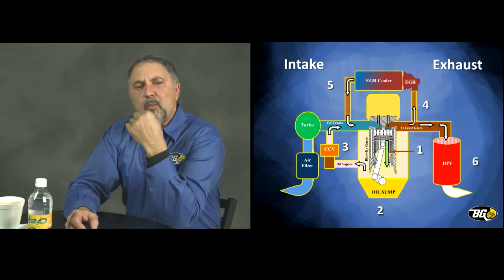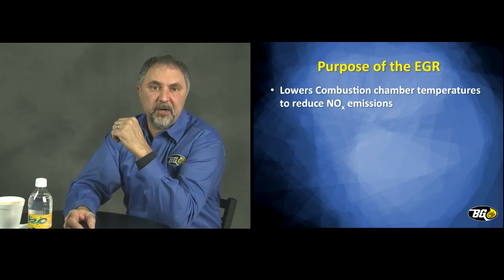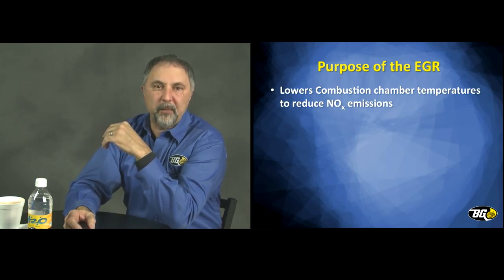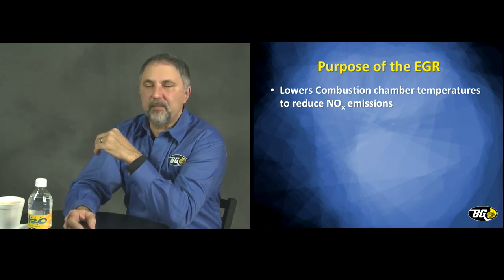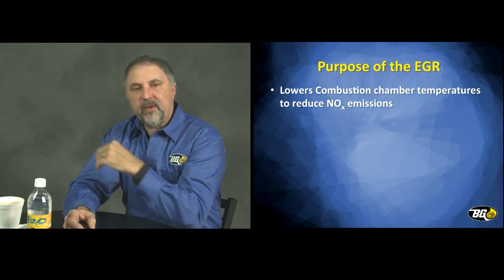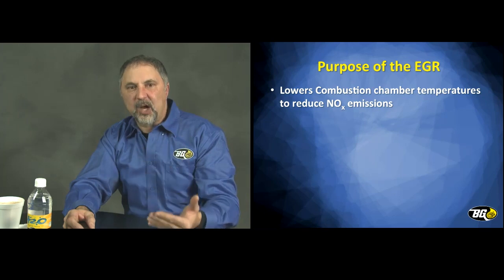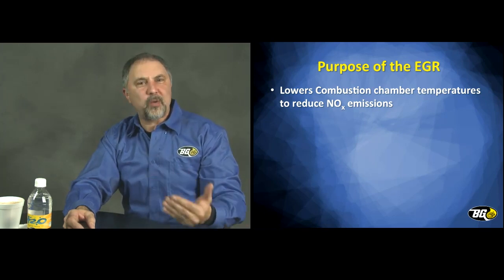Now, let's focus a little more on the EGR valve and its function in life. There are a lot of misperceptions about the EGR valve and its purpose. The purpose of the EGR valve is to lower combustion chamber temperatures. It's not meant to reburn the exhaust gases to help clean up the emissions. I often hear guys saying this in their demos, and it's not true. If you're not careful with your word tracks, and you don't fully understand the system while doing a sales presentation, and somebody out there in the field who's knowledgeable hears this, you just lost credibility.